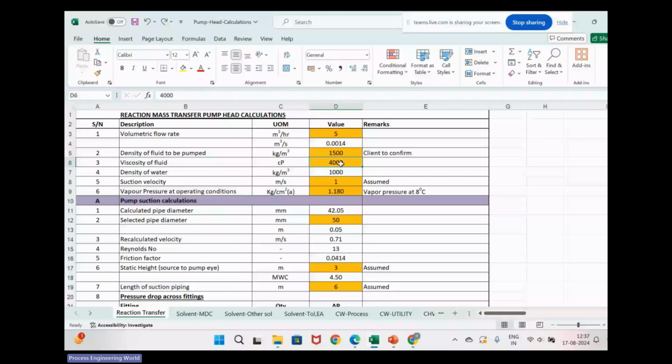So you want viscosity at atmospheric temperature, let's say, and at a higher temperature. At 2-3 points, they provide you the viscosity. So you can get this viscosity from R&D engineers or R&D scientists. They will perform an experiment in a viscometer, which is the Brookfield viscometer. You can note down the equipment name, Brookfield viscometer. It is widely used in industries.